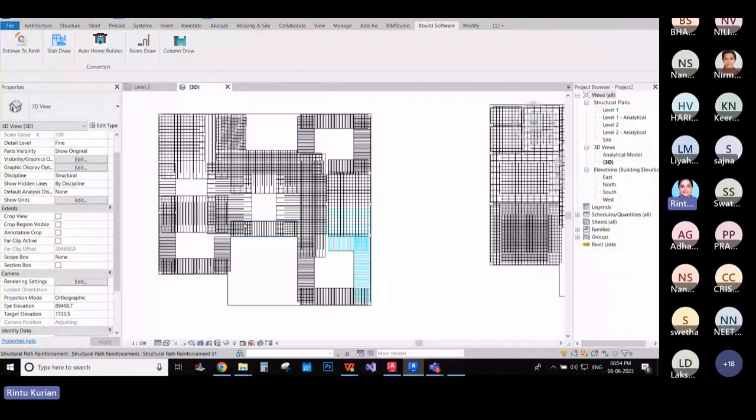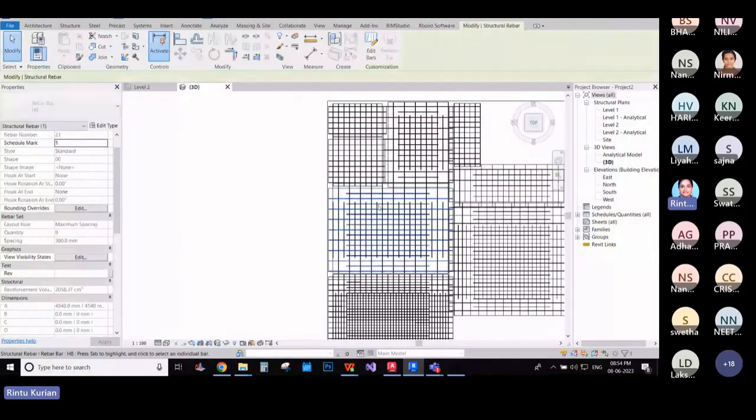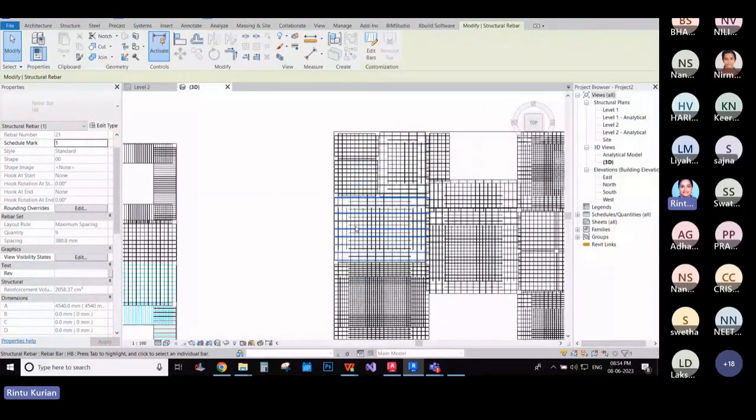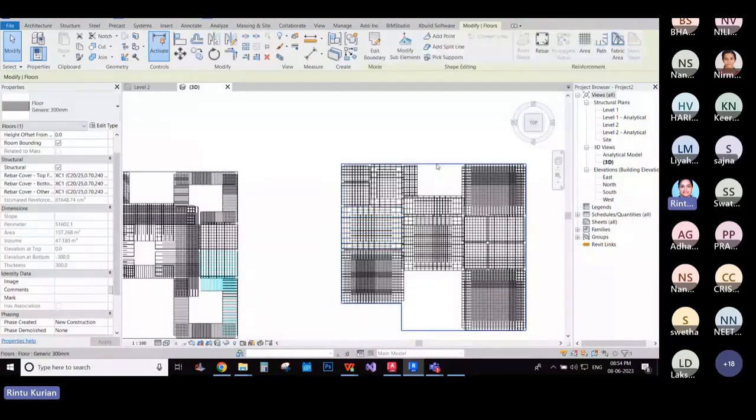For customizing alternate bars, bends and start and end, and all these things can be easily customized when you're using the path method. Now, what a path method is and all, you can find videos regarding the same in YouTube. I can also share some samples for the same. Now, we'll just check how to bring the beams into 3D using the same BBS data you have done earlier.